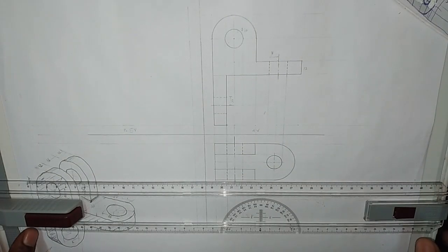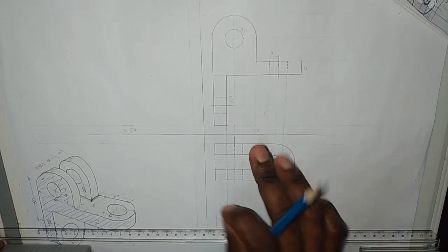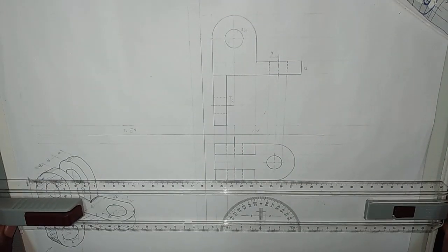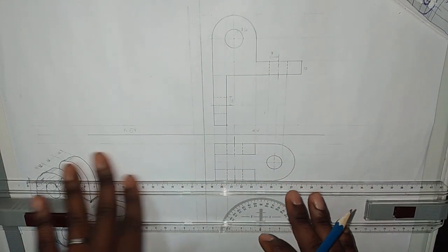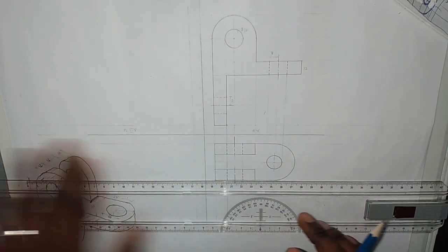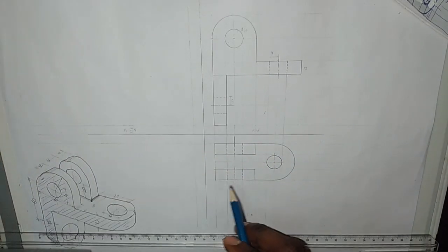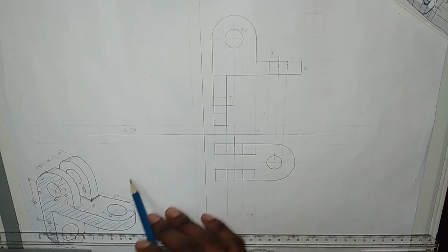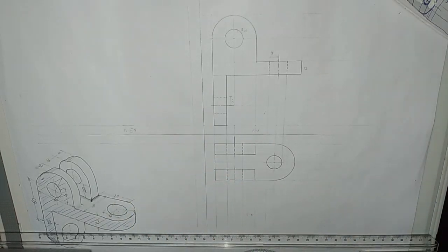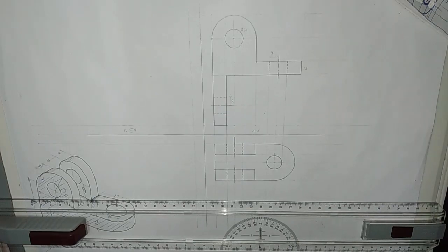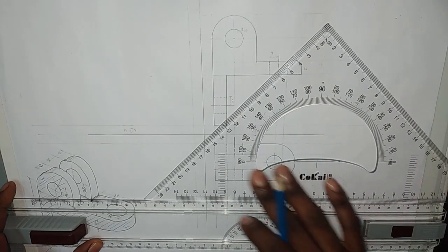So the next important thing, we have our top view now. This is our top view. Next important thing we do is to project horizontal lines from here to the left. Then draw a line of angle 45 degrees, this one or this one. I'm going to draw the line first and then draw my projection lines. So this is going to be my 45 line.